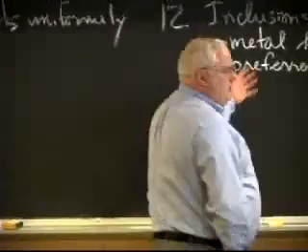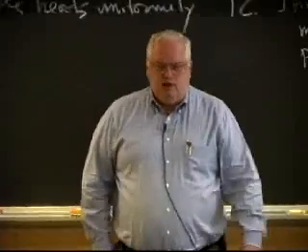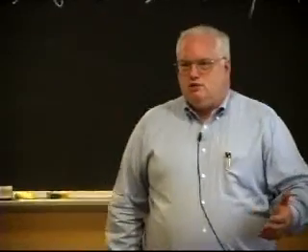I said, yeah, but I know it's not laser weldable because you've got a ceramic surrounded by a very reflective material. I'm going to preferentially heat the silicon carbide and decompose part of it. It's going to form aluminum carbide (Al4C3), which is attacked by water. So you're going to end up with a product that would stress corrosion crack, but you're also going to end up with a lousy joint, because you're going to superheat the silicon carbide and reflect from the aluminum. You're going to end up with a terrible weld.